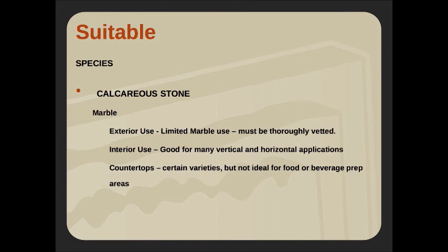So, all right, marbles. Exterior use, we've got to be very, very, very careful. There really aren't very many that I would say I'm comfortable with. Again, let's get with the quarry, let's get with the suppliers, and make sure that if we think we're going to use it, that we're using the right one. All in all, my general rule: marble, keep it inside. And most of them are going to be good for vertical or horizontal applications.